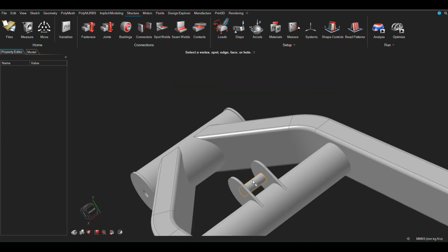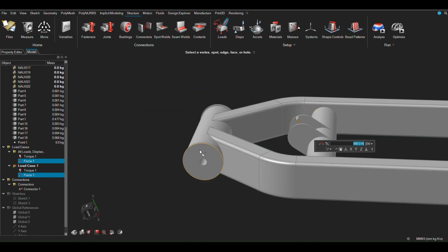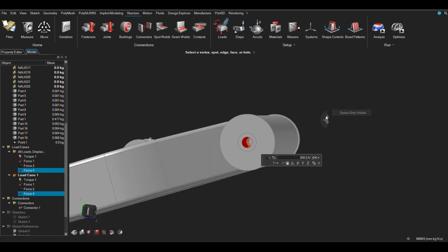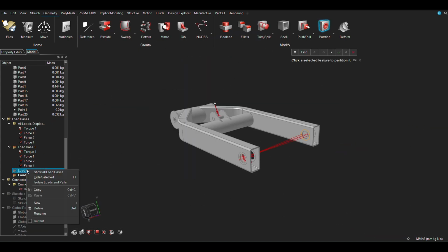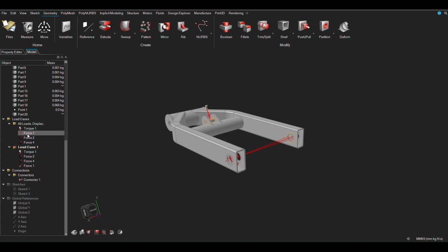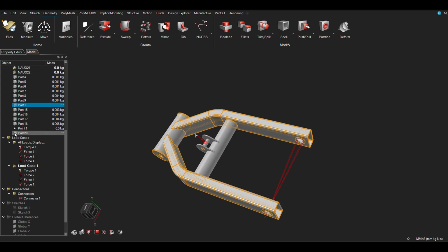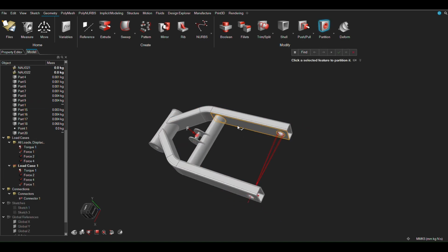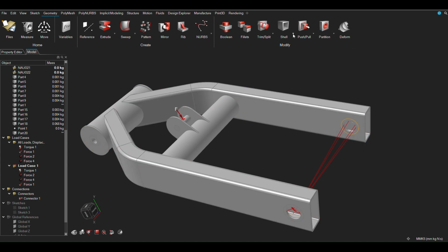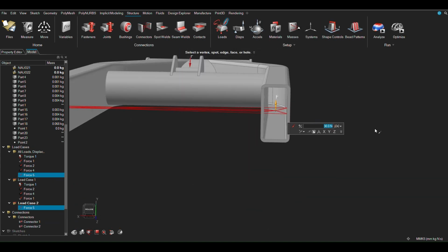I initially tried to perform topology optimization directly on the full swing arm assembly within the motion analysis setup, but it was taking a huge time. To solve this, I isolated the swing arm component and performed a static topology optimization separately. I reapplied the material properties, loads, constraints, actuator force, and the torque to replicate realistic conditions.